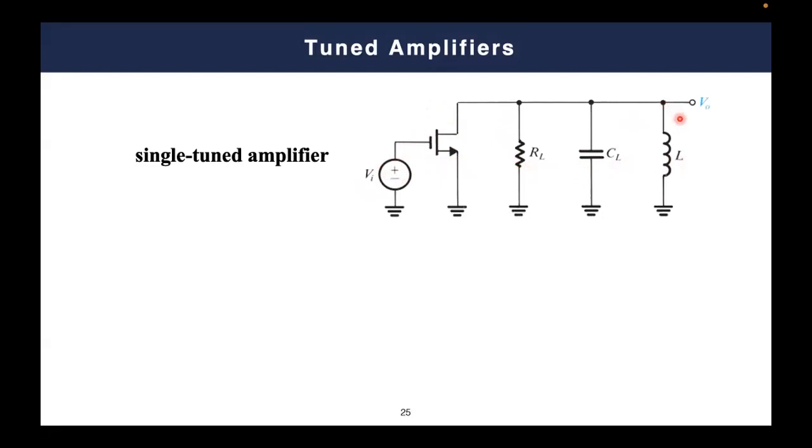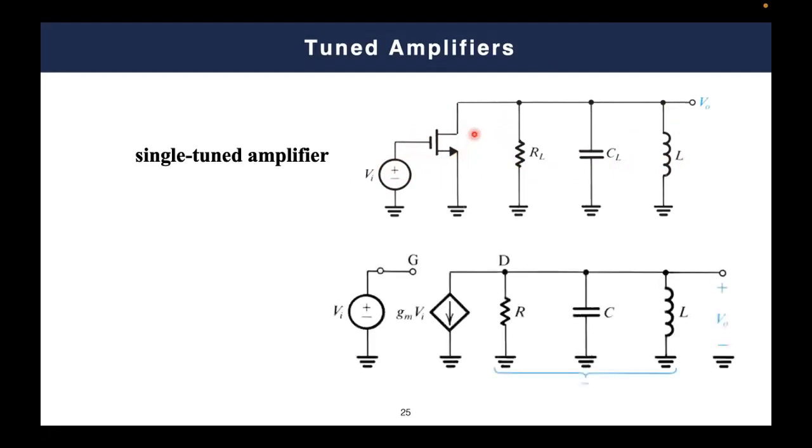In this case, if you remember, my dear students, we use what we call the small signal analysis in order to investigate this signal. The small signal analysis was based on replacing this MOSFET with its small signal circuit model. Let's remember together the small signal model. So simply, this is a small signal model. Here, this is the input and this is the gate voltage. As we all know, the current flowing into the gate is typically equal to 0 due to the oxide in the MOSFET.